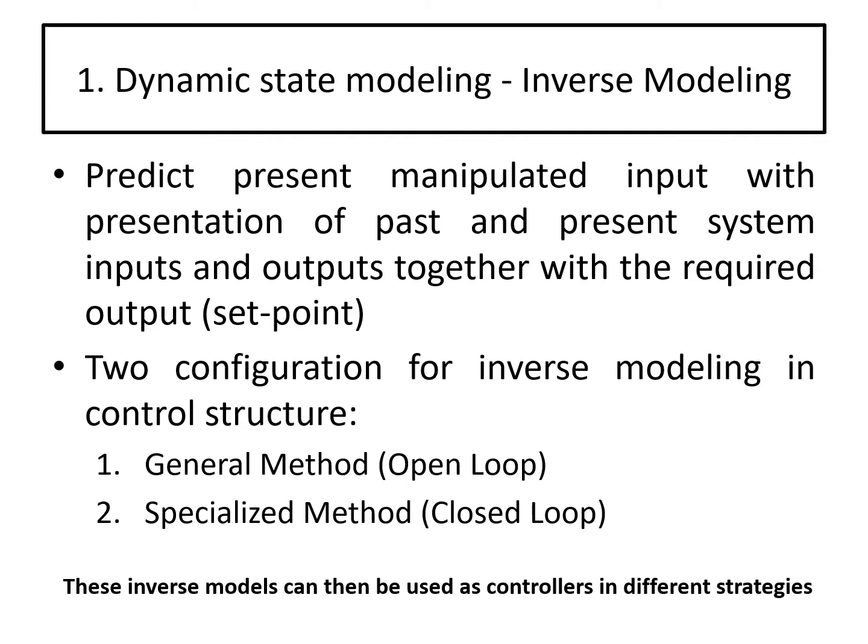Last week we had the last lecture, part 2A, the dynamic state modeling, which is made up of the feed-forward modeling, which is a normal modeling process where we put input, we get output. But we can also have what we call inverse modeling, the inverse of the model basically, when we put in the output to get the input. The normal modeling process to get the inverse may be complicated due to the nonlinear structure. The neural network is much easier to get. It's just a matter of switching the input-output data.